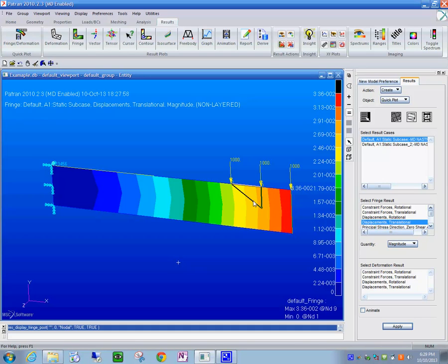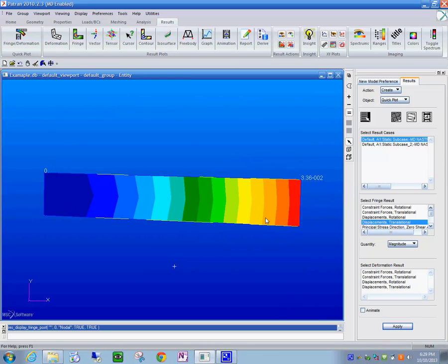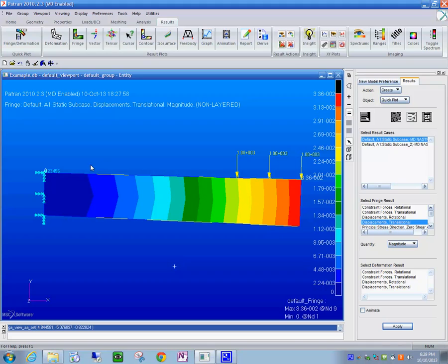So you see how the finite elements are. Every boundary of the color crosses 2 points on the triangular element. And those 2 points allow the computer to calculate which way it should color the picture, because the color is completely related to the level of the variable, the level of the stress, from dark blue to red, where red is the highest level of deformation.